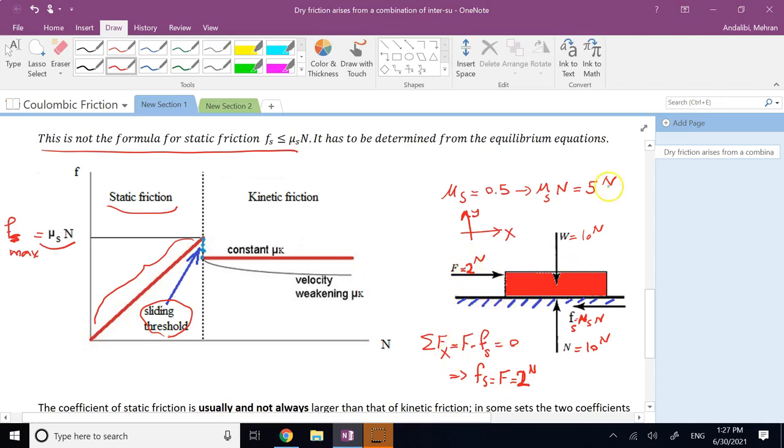But once you pass 5, which is the maximum capacity of generating friction, which again we call traction, the surface cannot keep up with you anymore. So when you go 6, now the surface cannot go to 6. And that's where your force is now more than all that the surface friction can exist, and now the object starts to what? Slide. When the object starts to slide, we call it kinetic friction now.